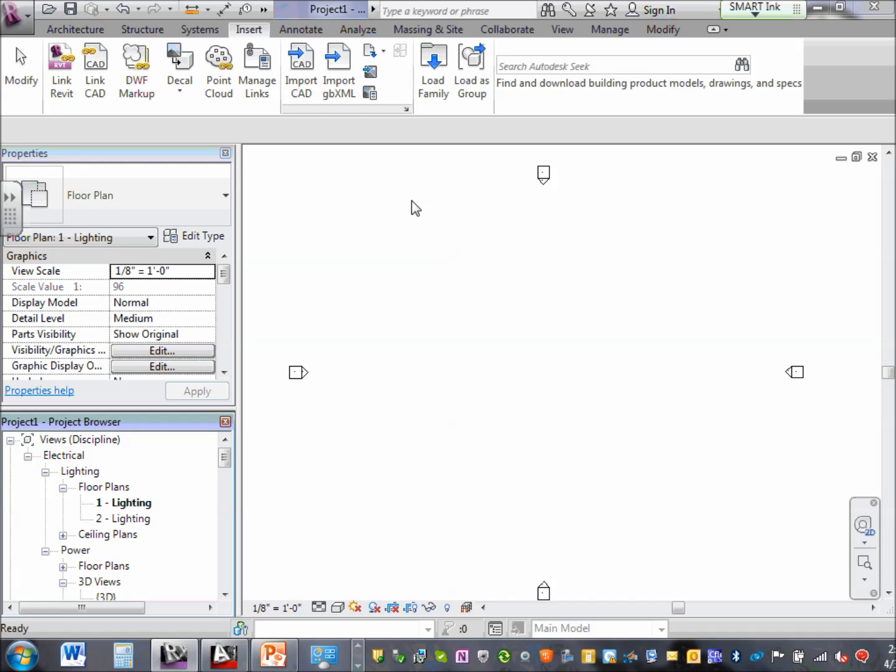Now, what is a link? The architects will have a model in 3D in one location. You will link to it, have a picture of it, and you work on it. You can't change the model. Typically, you can see what they're changing when they change things, but we can't decide which door we're going to move. So they have the model here, you take a picture of it, you start working on it, and they can see your work, and you can see their work. Mechanicals can also coordinate in the same big model. So that's what link is.